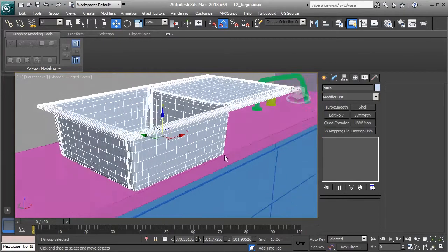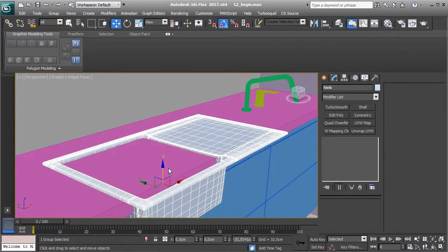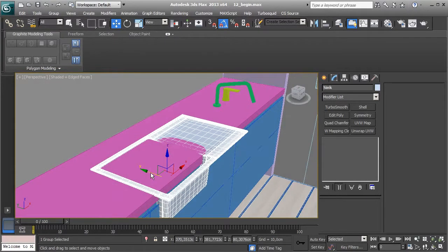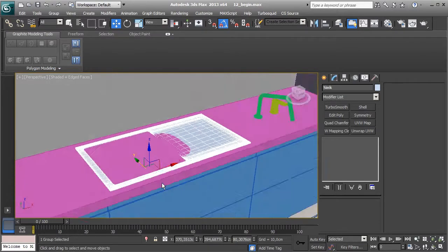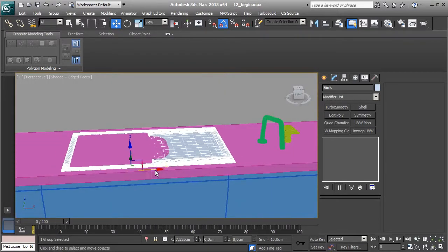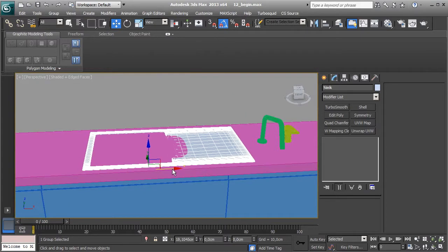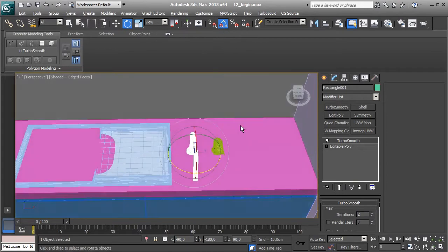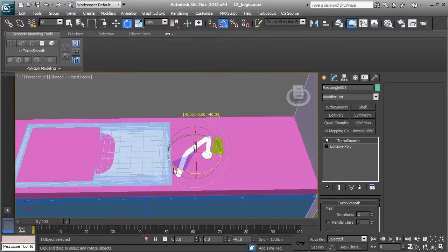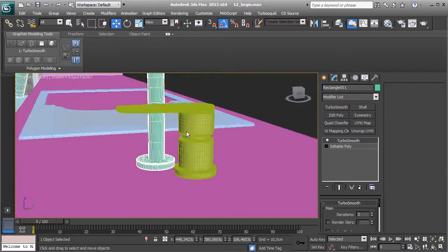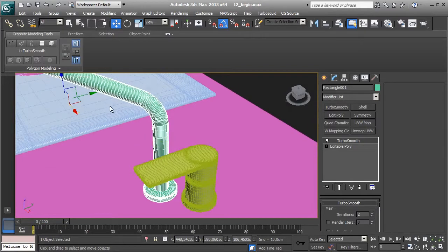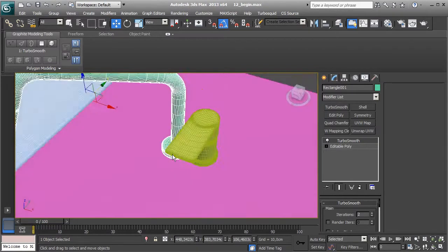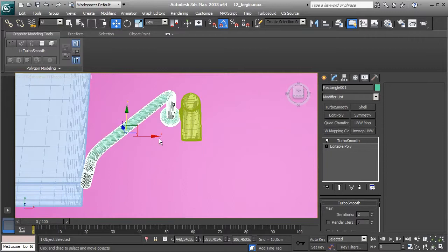Sync to the right place, push that down and move that here to the wall like that, and move that to the right like that. Now select this object and with angle snaps turned on, rotate that by 45 degrees. Let's zoom in and move that here, make a space between them like that.